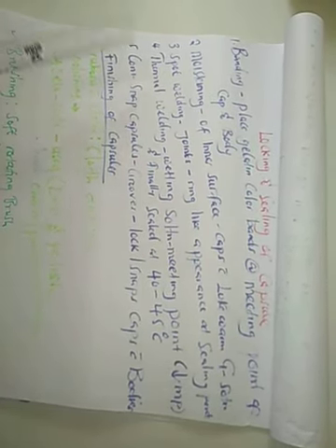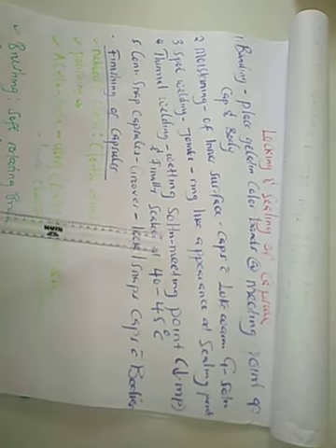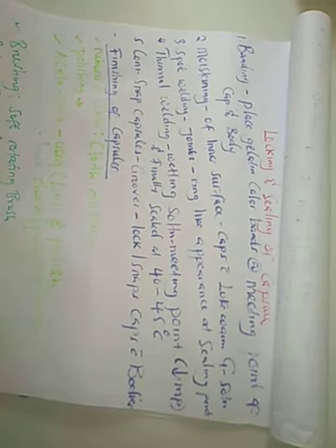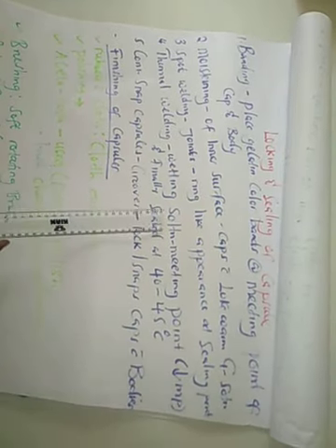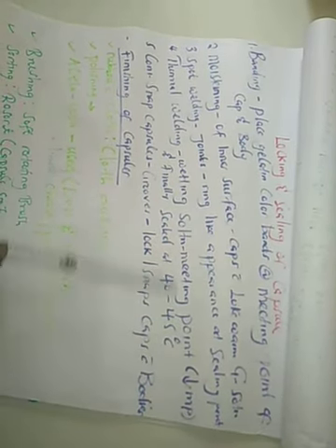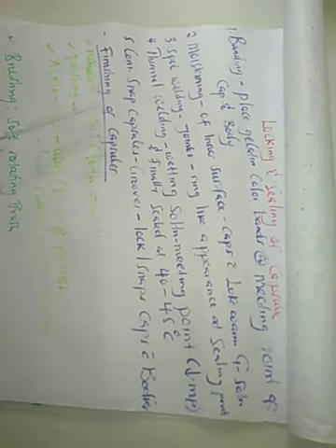Then there's also what we call thermal welding. Here, first of all, there's wetting or softening of the joining point. At the point where the cap and the body join, you wet them. Why do you wet them? First of all, to reduce the melting point. And then, after the melting point has been reduced, they are heated at 40 to 45 degrees. So one question, why do we use 40 to 45 degrees temperature?